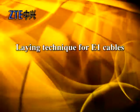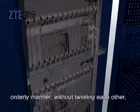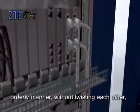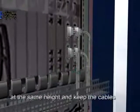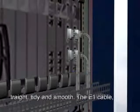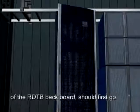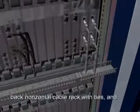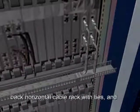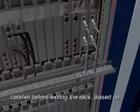Laying technique for E1 cables. Bind the cables near to the plugs in an orderly manner, without twisting each other, etc. Attach cable ties at each row of cables at the same height and keep the cables straight, tidy and smooth. The E1 cable, which leads out of the RDTB backboard, should first go downward and out of the plug-unplug location on the back card, be bound at the back horizontal cable rack with ties, and then enter the vertical cable trough of the cabinet before exiting the rack.